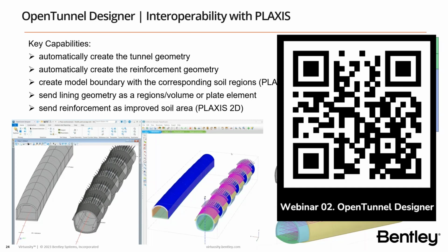And usually what they are doing is overlapping the high level of detail model with the one created by the geotechnical engineer so that they can keep track of any changes if they appear during the design. But if the tunnel template is created correctly and we don't have issues with the geometry, then whatever you have modeled inside OpenTunnel will go to Plaxis.